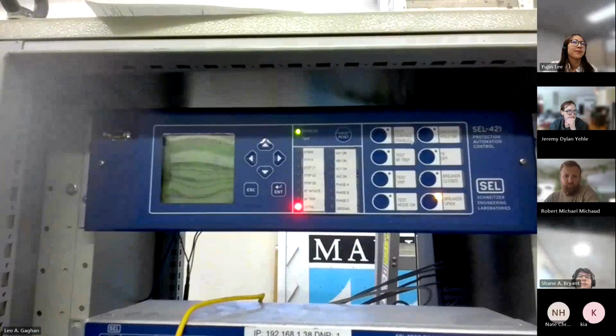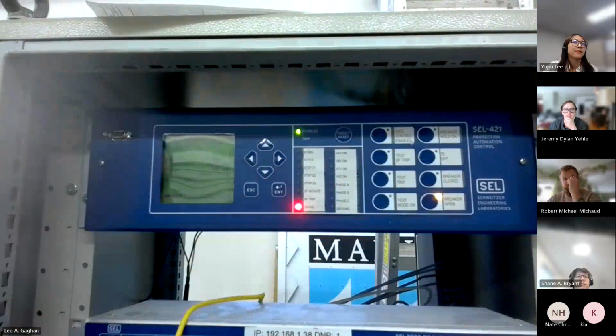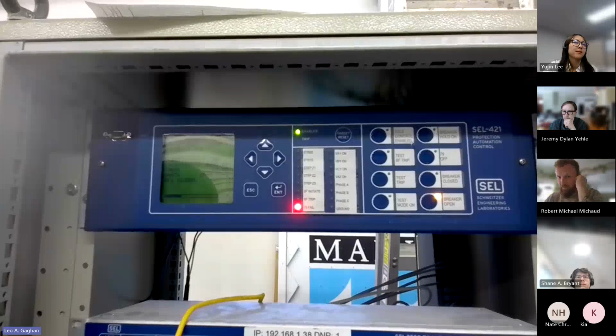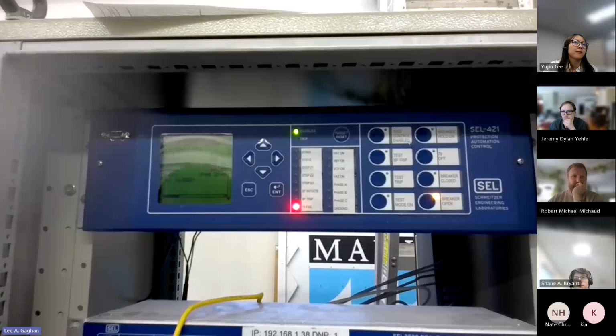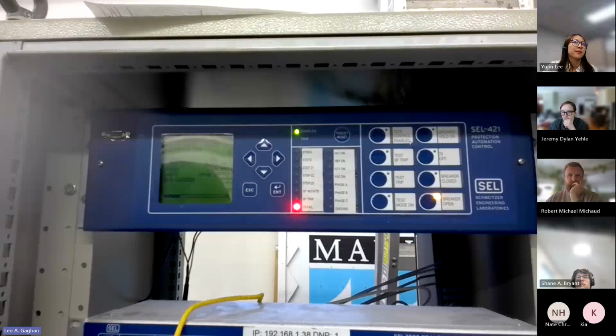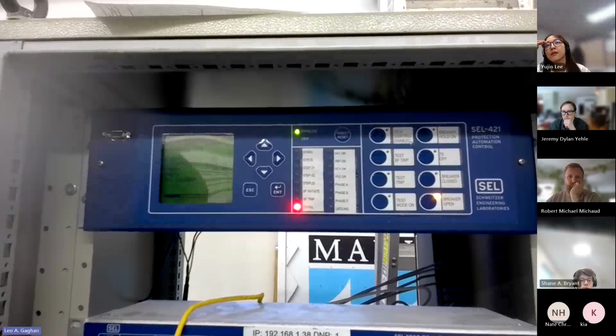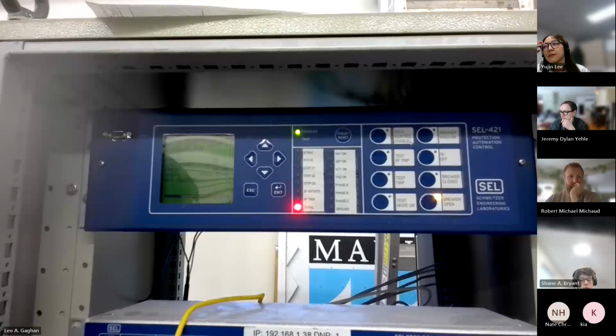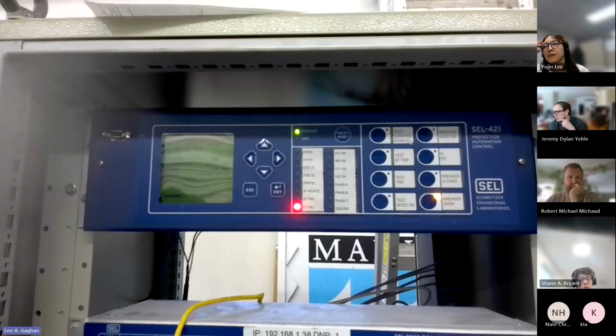Okay, so we're on sheet 2 here. And what we'll try and do is verify this trip logic. I'm going to try and really verify right now everything that comes in here. That word bit is called DK1, breaker 1, MTR, manual trip. So we're going to manually trip that breaker, and we're going to go through the processes that we just did.